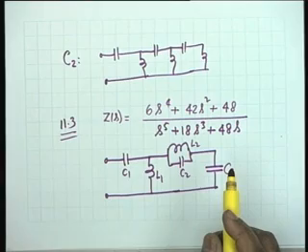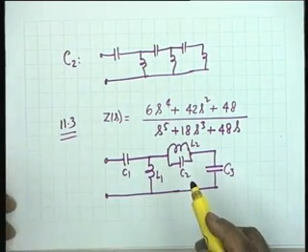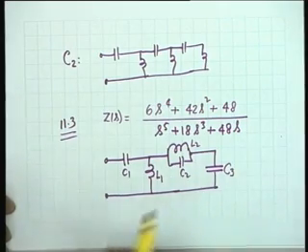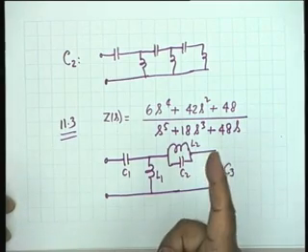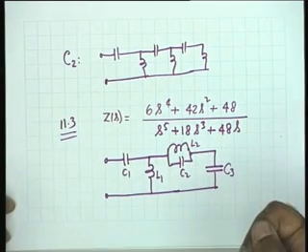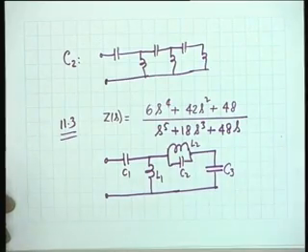Now, you can see that it is neither Foster 1 nor Foster 2 nor Cauer 1 nor Cauer 2. It is a combination. You can mechanize this. You can start with Cauer 2, go up to 2 stages, and then the rest of the function goes to Foster 1. All right. You can do that, or you can do it by successive pole removal.